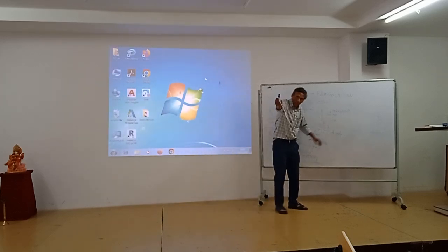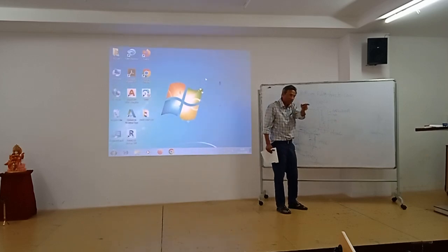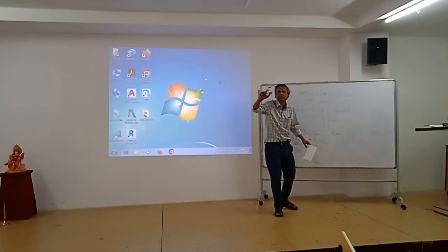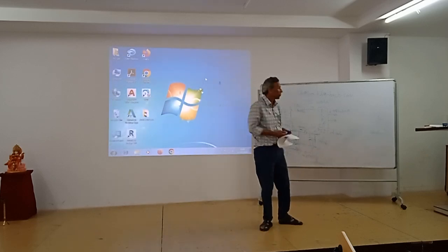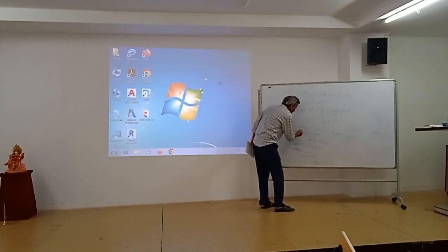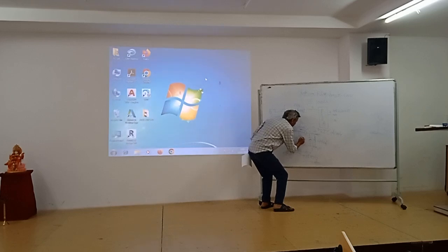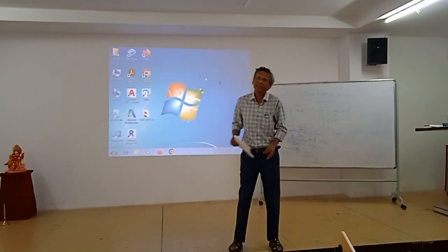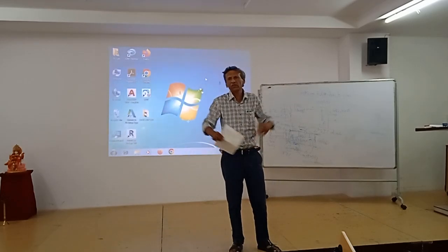Now you apply the same equation, the previous equation. From 50 it is 15,000. Suddenly your capacitor will be reduced. The only thing is, now this is 400, so I will write 450 volt and then say 47 microfarad. A small capacitor will be enough. So this is a major advantage. Forget about 6 lakhs microfarad, whatnot.